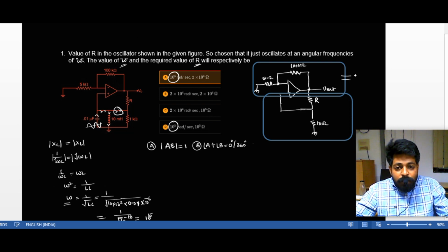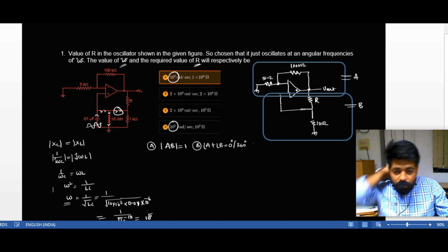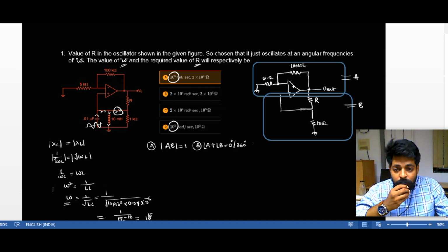This is my amplifier network. This is my beta network. And as I know, this is my op amp, where this is the minus terminal, the inverting terminal. This is the non-inverting terminal. And when my input is applied over here, and this is my input, I get the output with the strength of the gain of the amplifier, which will be around 1 plus RF by R.